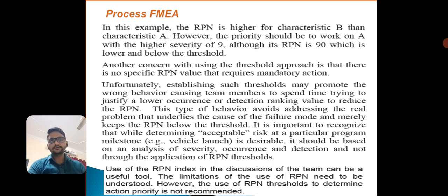Another concern with using the threshold approach is that there is no specific RPN value that requires mandatory actions. Unfortunately, establishing such a threshold may promote the wrong behavior, causing team members to spend time trying to justify a lower occurrence or detection ranking value to reduce the RPN.